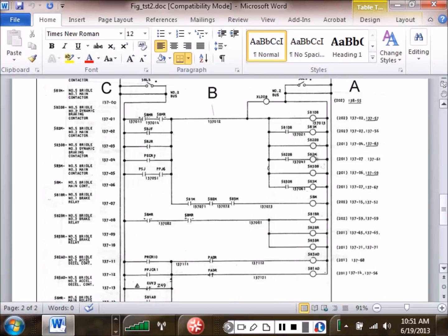We now get into commercial wiring and residential, especially when we get into cables. If you pull your own wire, if you pull your individual wires, then you determine the color of the jacket, right? Understand? If you buy a cable, then who determines the color of the jacket? The manufacturer of the cable. So when you go out and buy Romex, 14-2 Romex, it's going to be black and white and no jacket. If you buy 12-2 or 12-3, it's going to be what? Black, red, and then either green or it's going to be clear, depending on what you run.